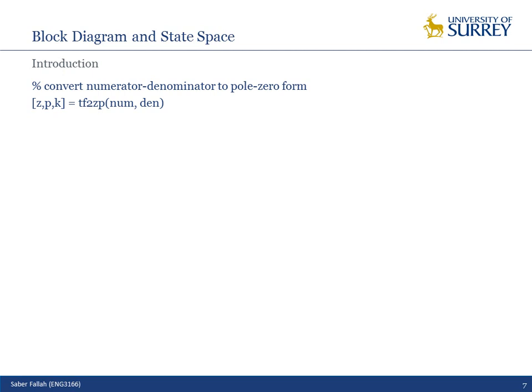How did you calculate the pole location of your fourth order system? You use the MATLAB root command, yeah? Or you can use this tf2zp to find the zero pole locations of your transfer function. But it's the same. If you use either of these commands, you will get z is empty because there is no zero, poles located at -3, -2, and -1, and gain 6.